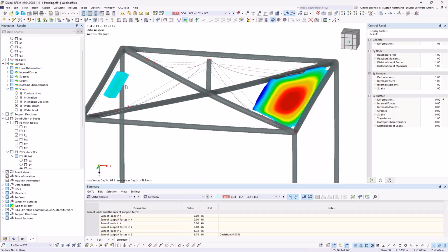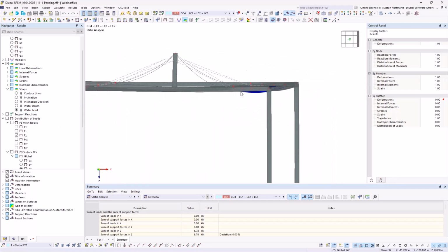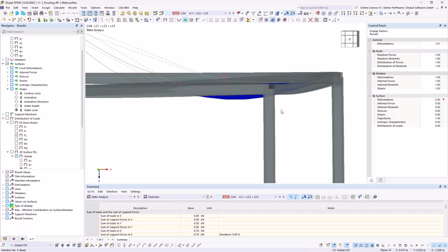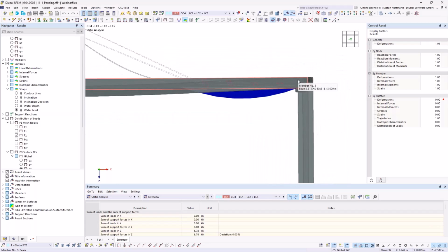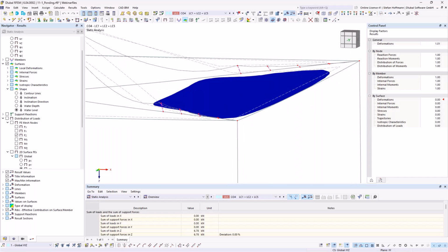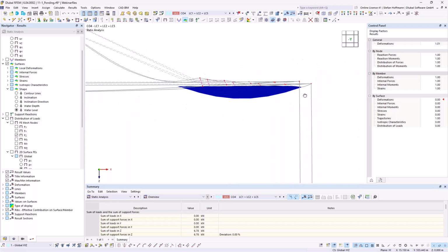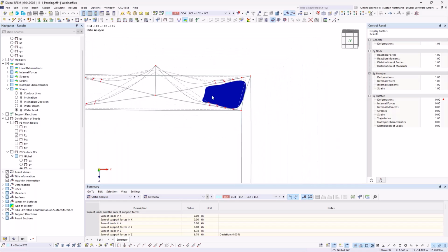And last but not least, it will even fully fill my hole, and I will then receive a final result. It will not influence the membrane with its stiffness and the pre-stress more, because it will afterwards just drop down at the edge, as you can see over here, where the member is a 1D element, so it will not take into account the height of the member. That's not possible in a 1D, but it will now flow down, and this is then the state of equilibrium.